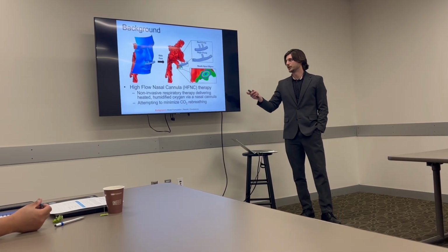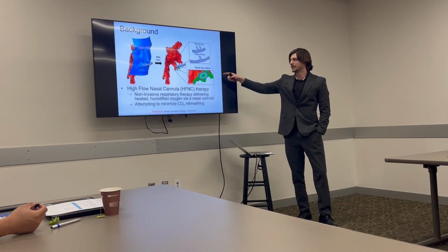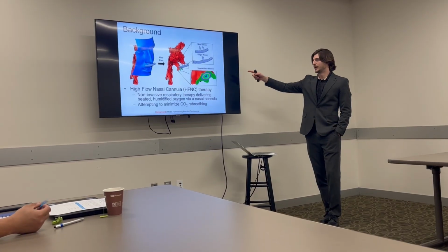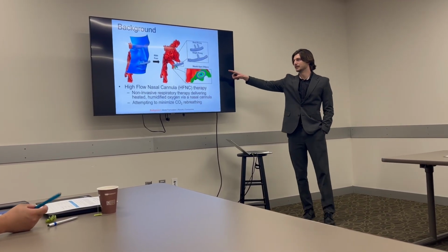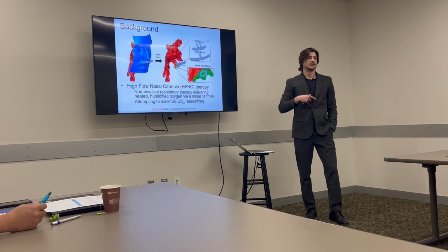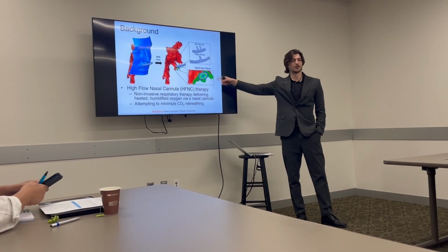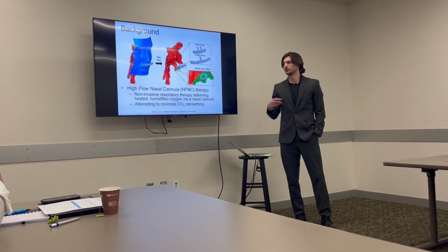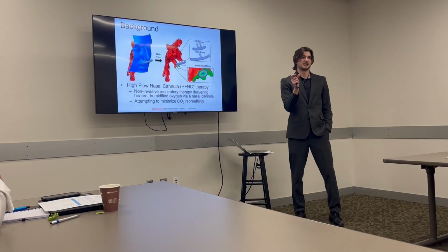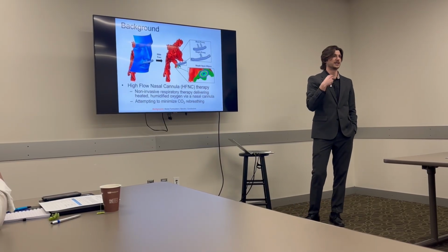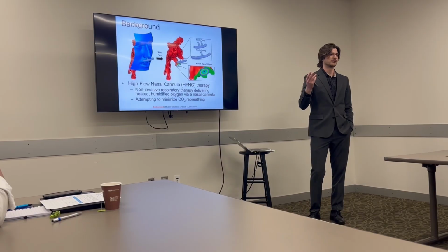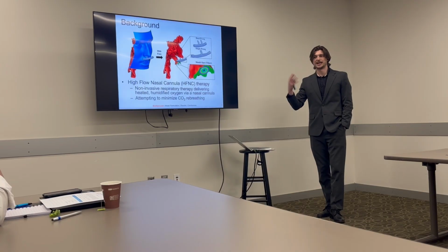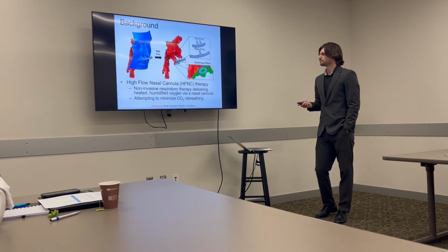So rather than remeshing, prior to meshing, we split an interface just behind the patient's teeth into a variety of surfaces here, and each of these ellipses relates to a different percentage of the surface area of this total interface. So if we wanted the mouth to be 5% open, for example, we would set the smallest ellipse in the center to an internal face where it would be invisible to the flow, and the rest of them would be walls. So this was our procedure for changing the mouth opening rather than changing the actual domain being simulated.